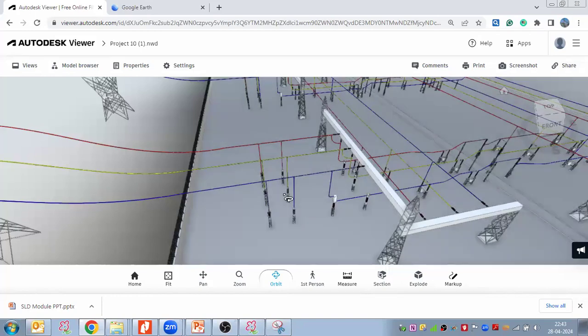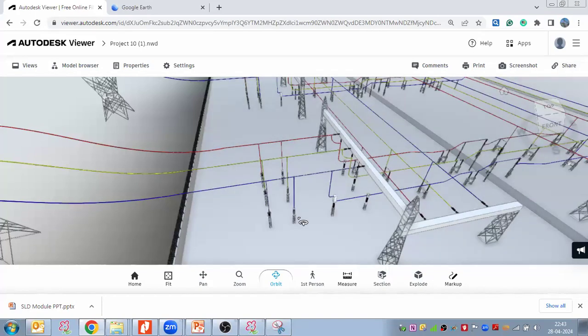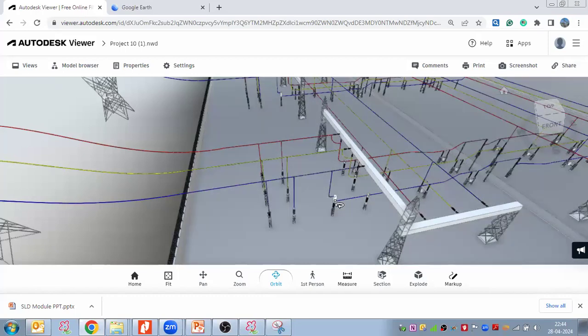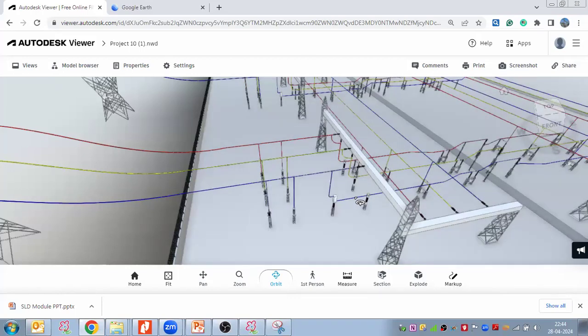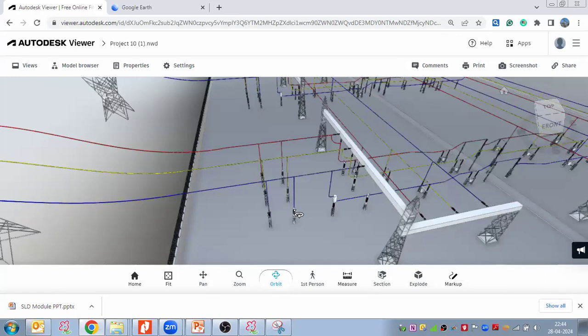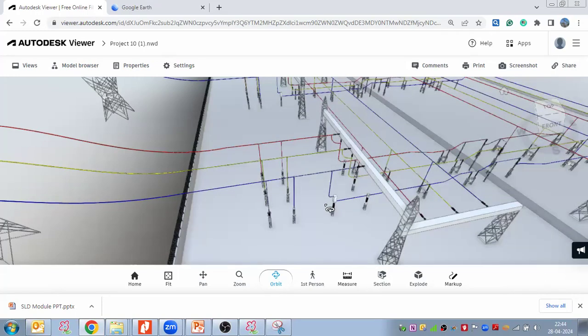No CT in that, because as per the specification we received from the client, they are saying that a CT should be required for the tail end protection, tail end protection for the 400 kV line. See, CT would not be here. CT should be after the disconnector. If you have the wave trap, then before the wave trap. If you are not using the wave trap, then CVT first will come. After that, you can take the CT, and that CT we take for the T protection.